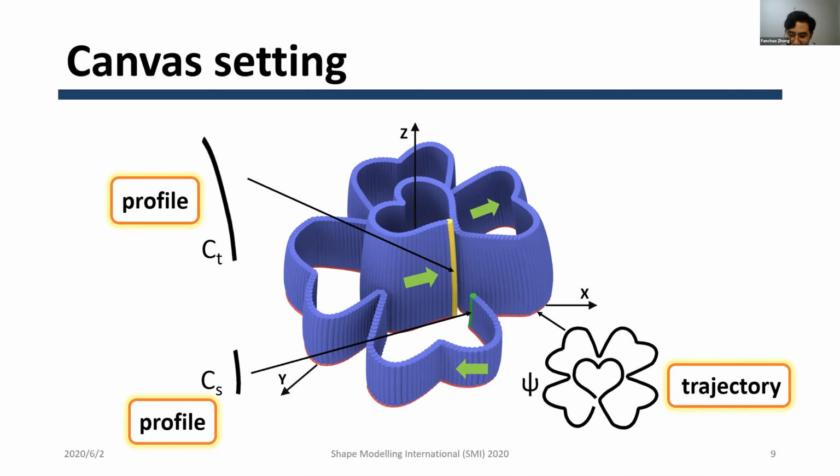As you can see, the CS is located at the starting position of phi, and the CT is located at the end position. The average transition curve is obtained by interpolation, located at one of the points on phi. In the figure, each blue vertical line represents a transition curve.